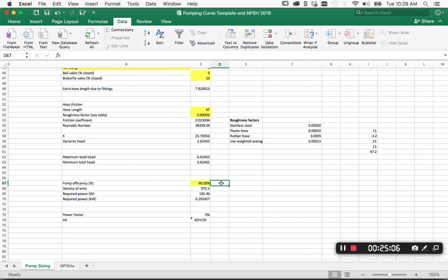So you just find a pump which will do 6.62 metres of head at your desired velocity and put that into your report and just say, I'm going to use this pump because I want to pump at this volume an hour and this pump has this amount of head, and this pump will overcome that head at this power rating. So that's all pretty simple. So that's for the fixed line.